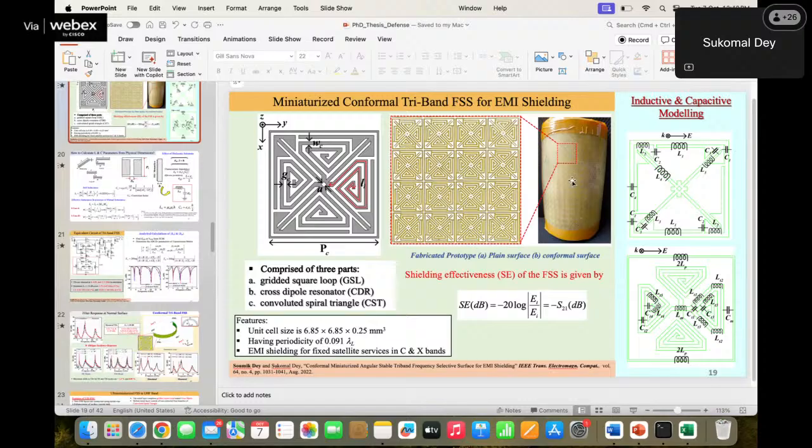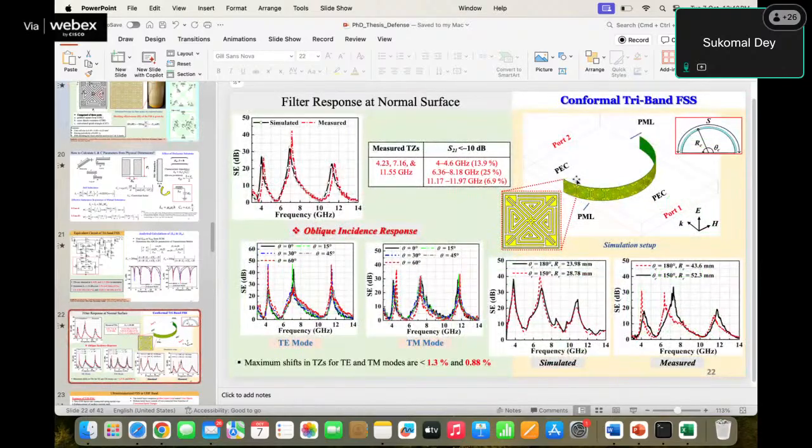To simulate the conformal FSS, you cannot use a single unit cell; there you won't get any conformability. To make the structure conformal, you have to conform it based on the given radius, and then start your simulation. Here you can look at the electric and magnetic field and the wave propagation vector. With that, your structure is basically growing on top, making an array.